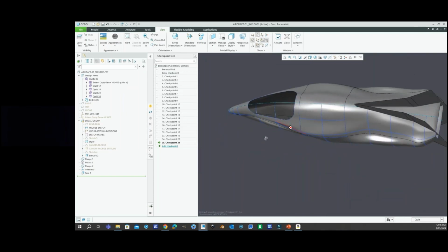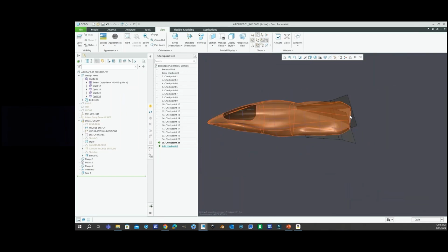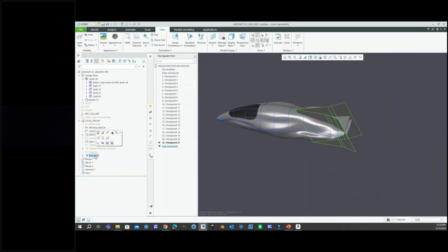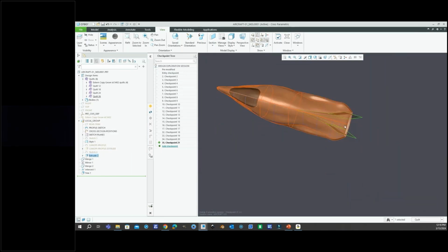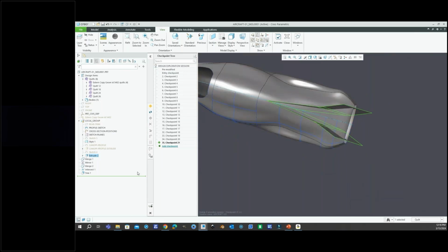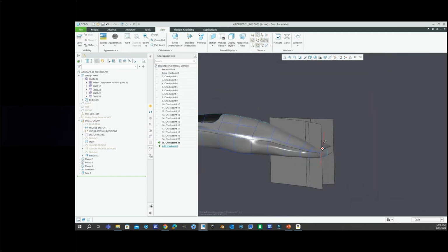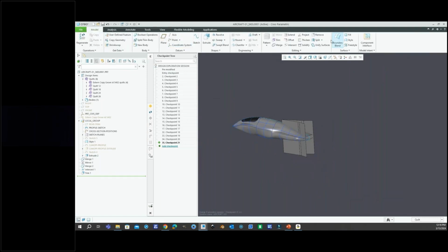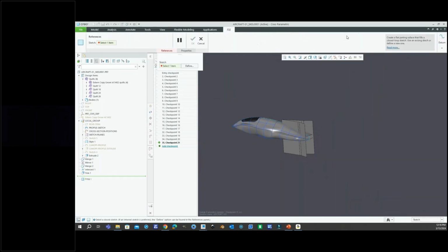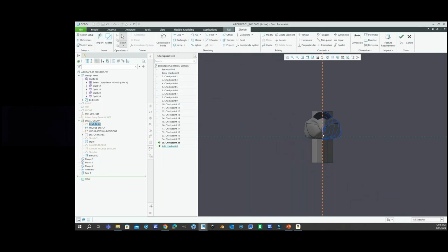Okay, great. All right, so now what I'm gonna do is, let me also take a look at this guy, and I'm gonna actually trim this, but what I might wanna do is create another merge here. Let me take a look, rear trim. Okay, so let me do this. I'm going to grab the fill tool, and I'm gonna select the rear trim plane that I have there.